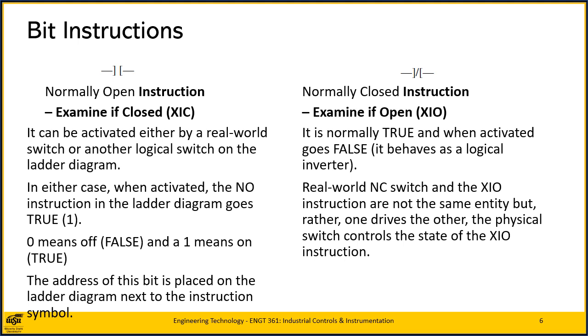Care must be taken when using this instruction in conjunction with a real-world normally closed switch, because it may not behave as you think. The problem is that people lose sight of the fact that a real-world normally closed switch and the examine if open instruction are not the same entity, but rather one drives the other. That is, the physical switch controls the state of the XIO instruction.